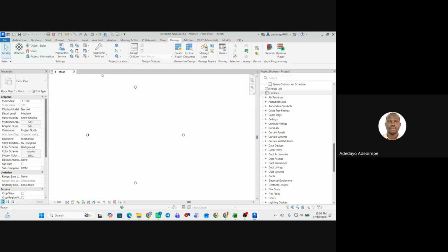They just work on the model, like they just create their own. So your architect can give you a base point. What do I mean? A base file that has the coordinates of the building, in which you model your project, develop your site, and now start modeling whatever you want to model as an architect. Are you getting it? So if you are working with an architect that does not understand all these coordinate systems, geographic systems, they may not make your workflow easy and good to work with.